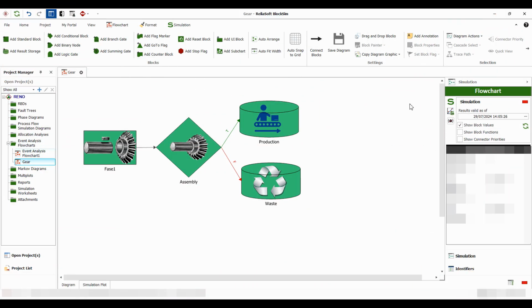In this video, we're going to look at a very simple production model. What we want to do is assemble a shaft and a key, which are both manufactured, machined or sourced externally, with dimensions and tolerances, so it will be a diameter and a standard deviation in terms of tolerances. The same thing happens for the key. We want to assemble those together and measure them and see how many of them will actually fit into this gear, knowing that all these parts will have their own dimensions and tolerances.